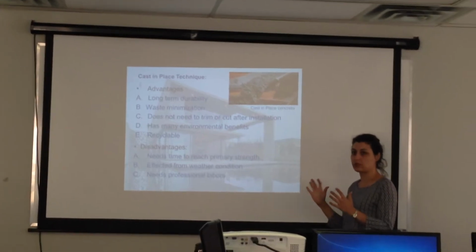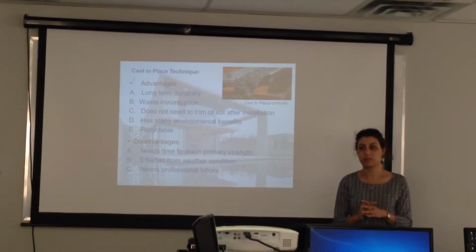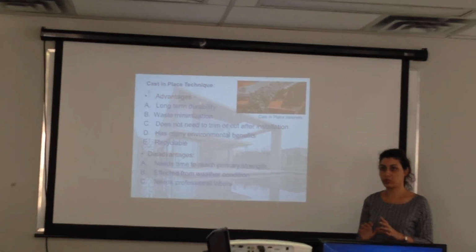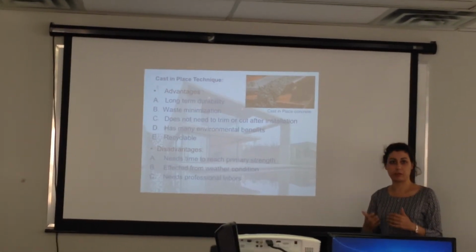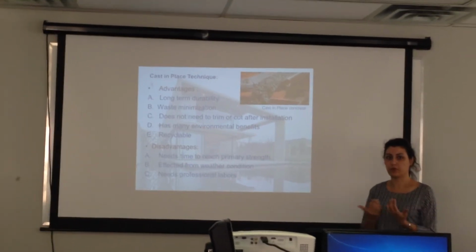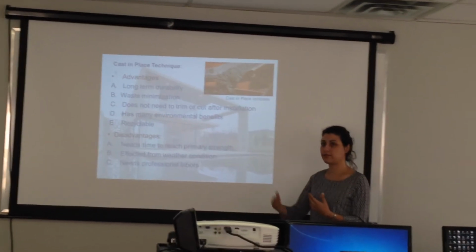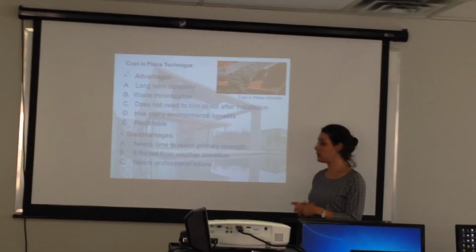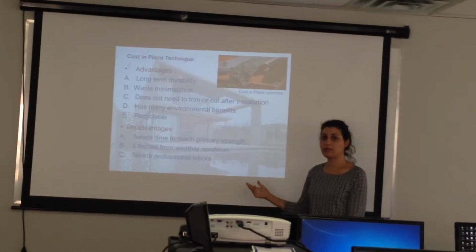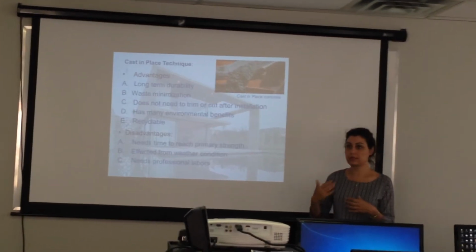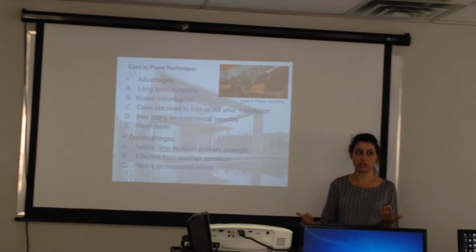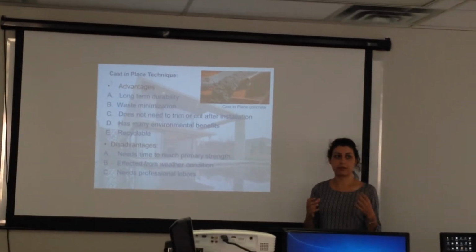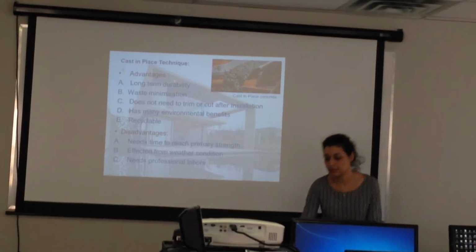This method is very related to the weather, so we should control the condition of production, warming the surrounding environment, or making it cool, or adding water to it, so it's very dependent on the weather. And the labor that installs this concrete with this method should be professional, and should have the basic knowledge of doing this job.